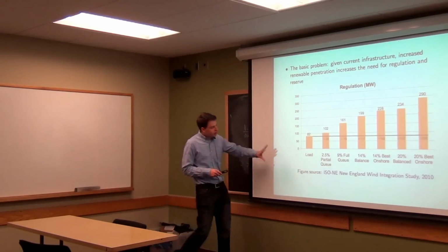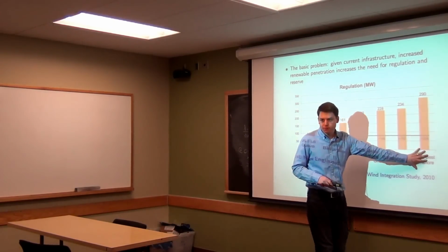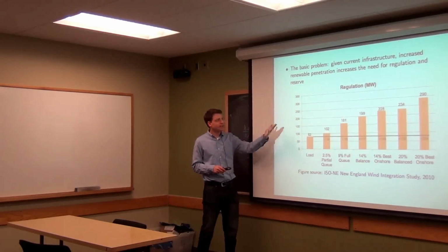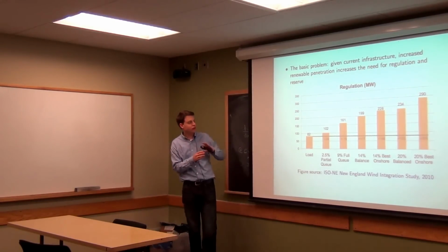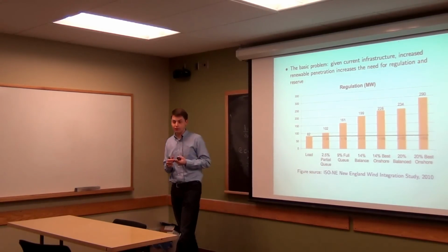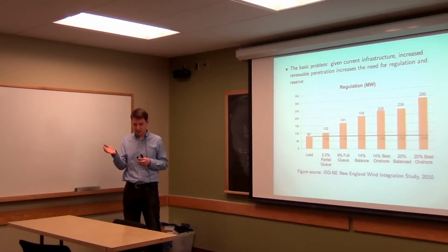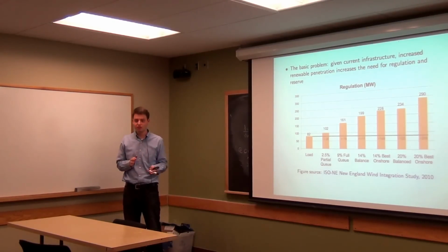What this study showed, though, was that for different amounts of added wind power, how much more regulation is needed. There are two types of added power, and I'm going to show one slide for regulation and one slide for reserve. Regulation is the very, very fast response, things that can come in within 4 seconds and start bringing stuff up and down. Reserve is more like 10 minutes.